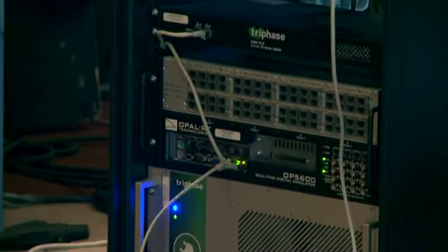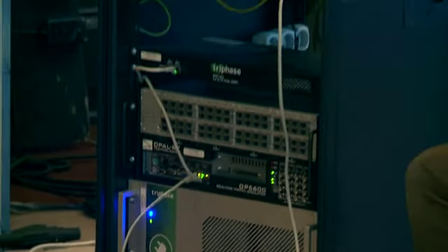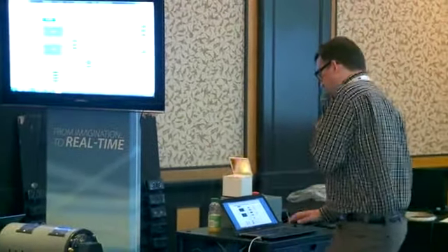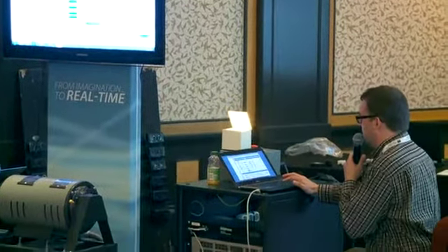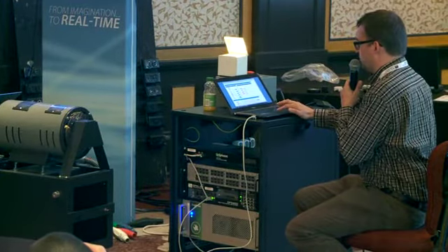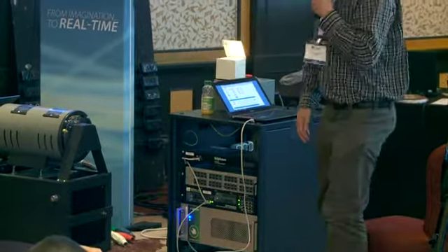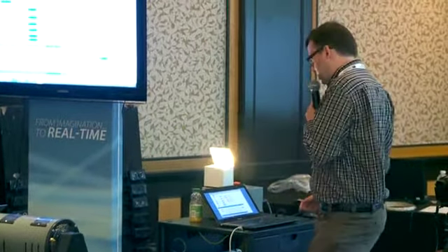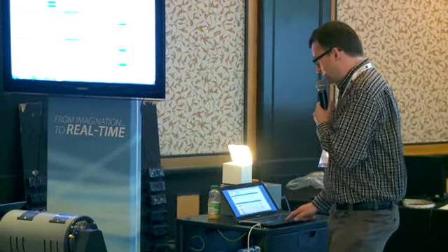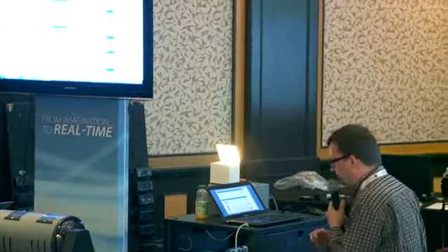So this is actually the simulation. This block is part of the amplifier control in the sense that it compensates for amplifier non-idealities. And the block on top is the actual simulation, the actual model, with a quite simple state estimator which estimates the impedance characteristics of the light bulb, which is a heat-varying resistor, and then a quite simple network emulation, because it is a simple network, so it doesn't require that much.